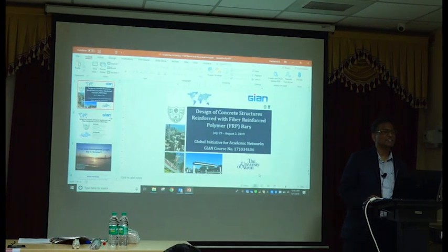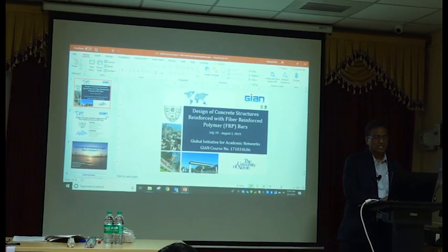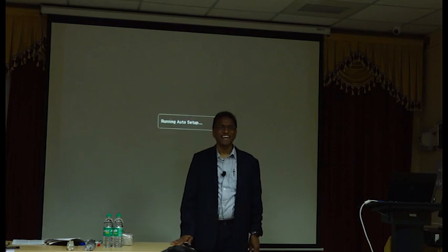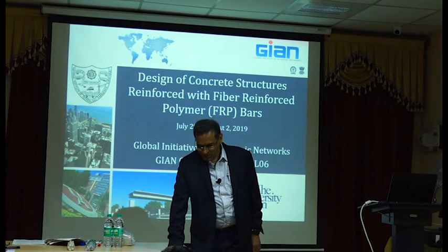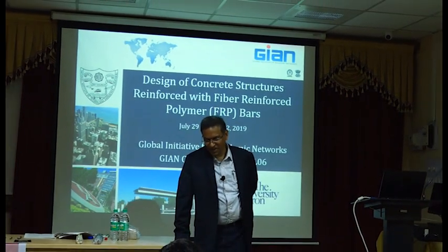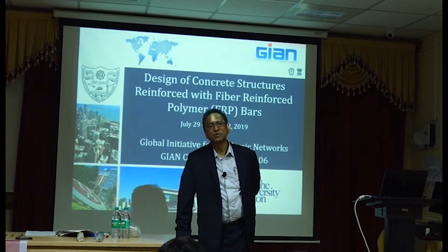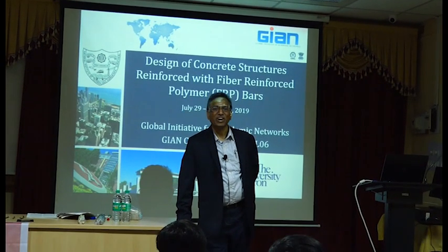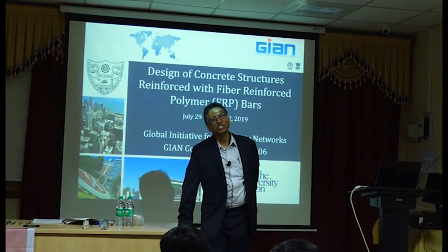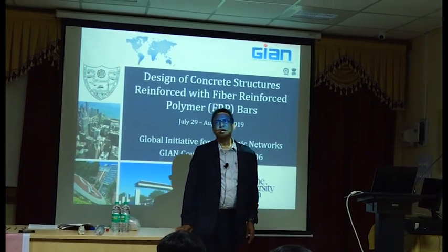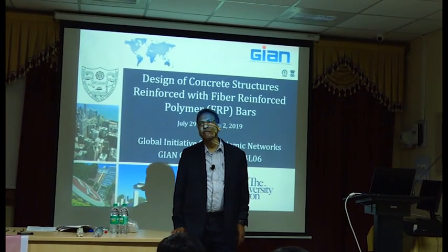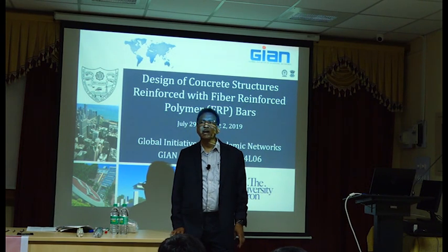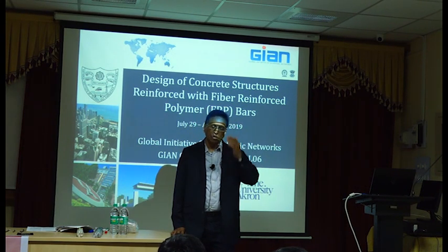The coefficient of thermal expansion for concrete and FRP are not the same. Right, that's true, I agree. But not all concrete members are subjected to so much temperature differential, so normally it should be okay. That may be a problem in pavements. What kind of temperatures do you expect in your pavements?